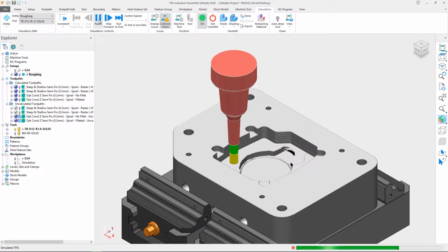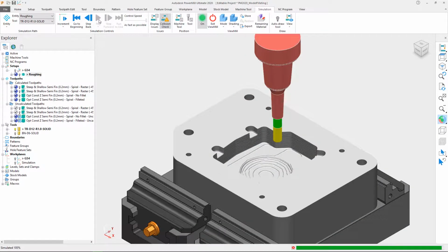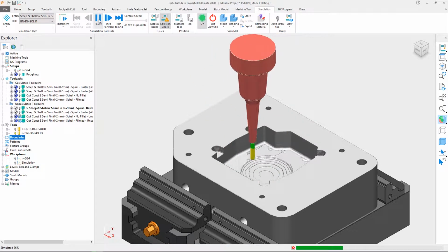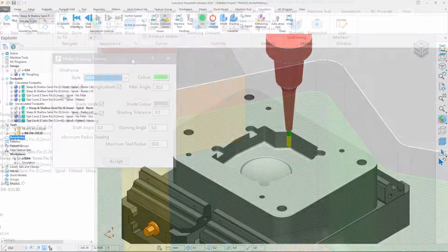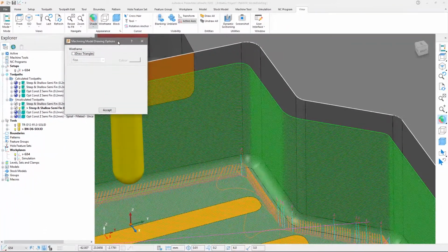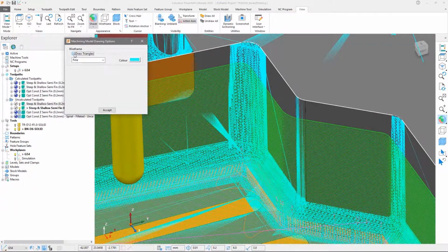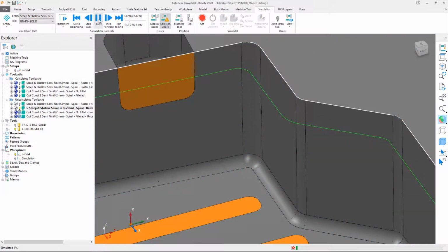Technology sharing across Autodesk products means you get the benefit of some feature developments from the wider Autodesk portfolio. The latest example of this in Autodesk PowerMill 2020 is the option to calculate a triangulated fillet model, which can be used during toolpath calculation to allow smooth arcs to be added into the internal corners of a toolpath to help protect your tools and preserve feed rates.